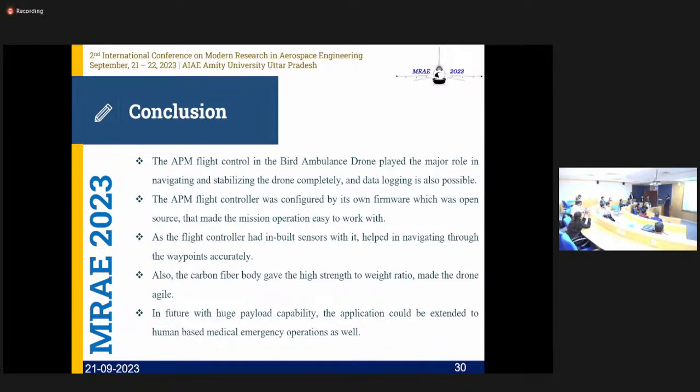Once again, the limitation of the drone is never the software or the motor. The motor can also work for a longer time because I'm using this motor for an agriculture drone as well. The limitation is because of the battery. Like I said, the battery time is 20 to 30 minutes at most. And I'm speaking about a 6S battery, not the small ones which people use, 2S, 3S, I don't know, that is like 15 minutes. A 6S battery will give you the best.